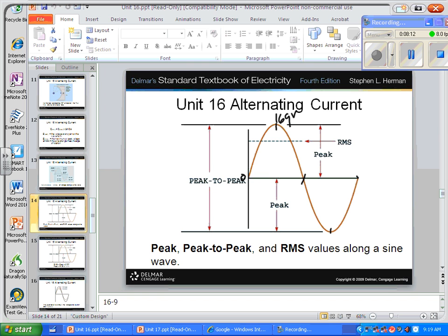That's what AC does. It falls to 0 how many times a second? Once, twice. Falls to 0 twice a cycle. Not a second, a cycle. And here in the United States, we generate power at 60 cycles a second. So how often does AC fall into 0 if it's twice every cycle and there's 60 cycles a second? It's falling to 0 120 times a second. And it creates a noise that you'll begin to recognize. You'll be able to hear 120 cycles a second. Because when you hear a magnetic coil chattering, it's chattering at 120 times a second. It's jumping back and forth instead of being held in. We'll talk about that later.